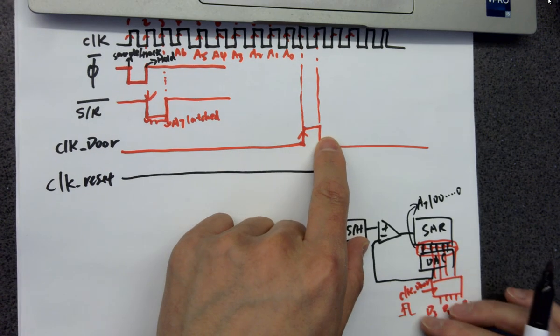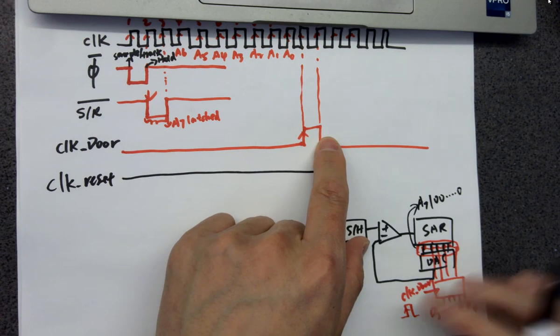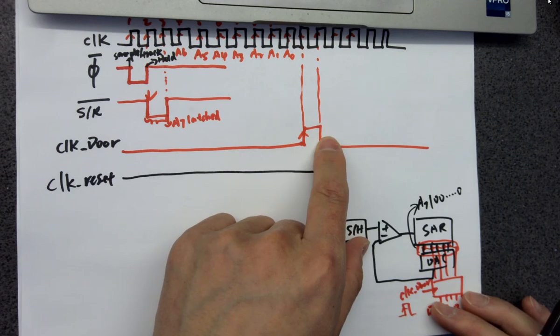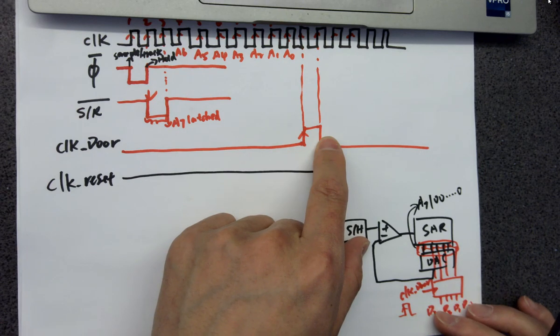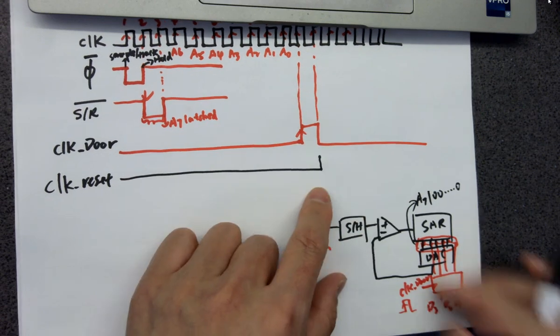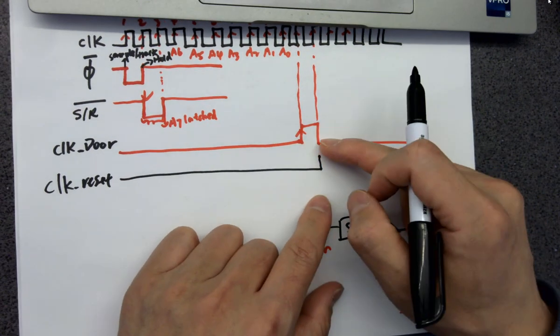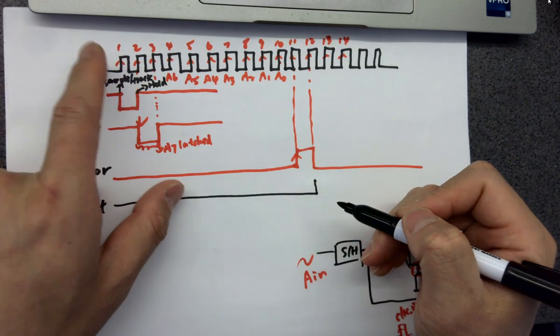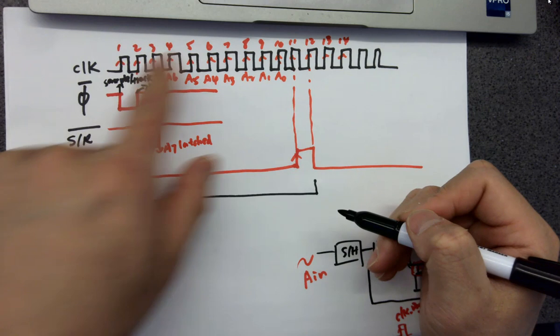It's just waiting for anything externally to sample it, to take it out, like parallel input or something, or serial like SPI or UART. You can shift all these into a serial-in, parallel-in, serial-out, no matter what. So the mission of the ADC is done. Eventually, after this, you can start a new one. You can reset the counter, so it's able to count from 0 to 11 again.